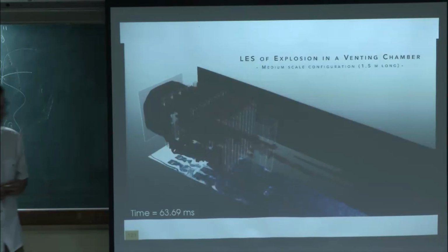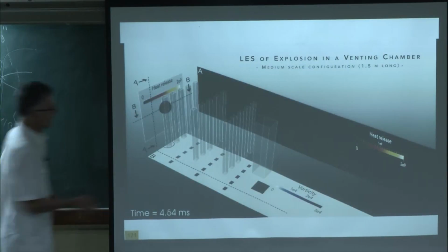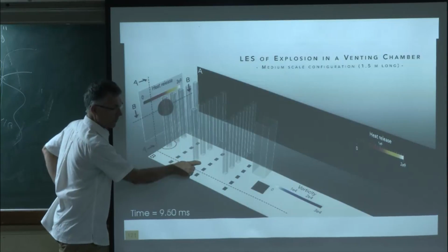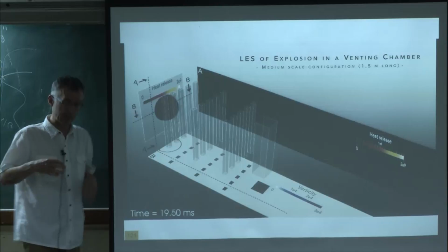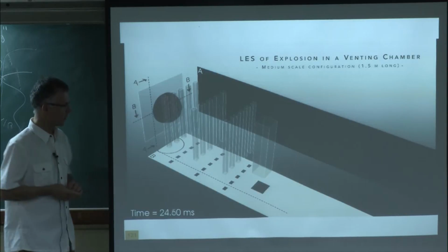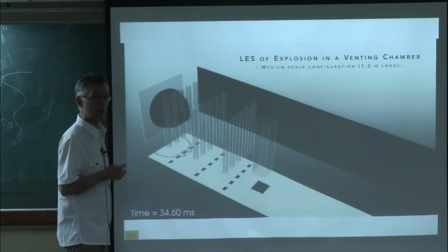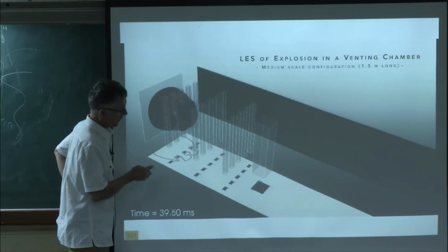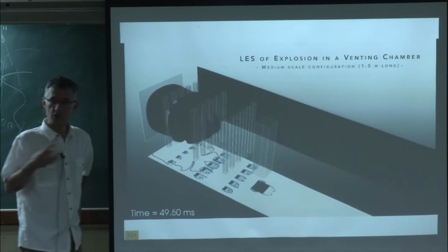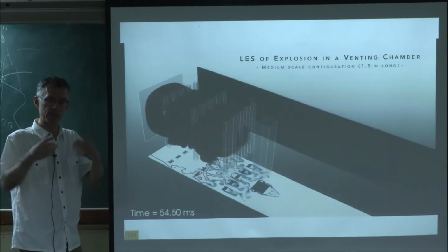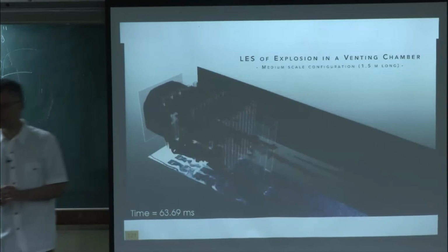And the trick in this simulation is that long before the flame reaches that point, the flow has already started moving because of this blast effect, the fact that the flame is pushing away the fresh gases. And that's very important, as you will see later in the talk, because it's actually accelerating the flame without any turbulent combustion mechanism. The flame is creating its own turbulence and leads to this kind of behavior.